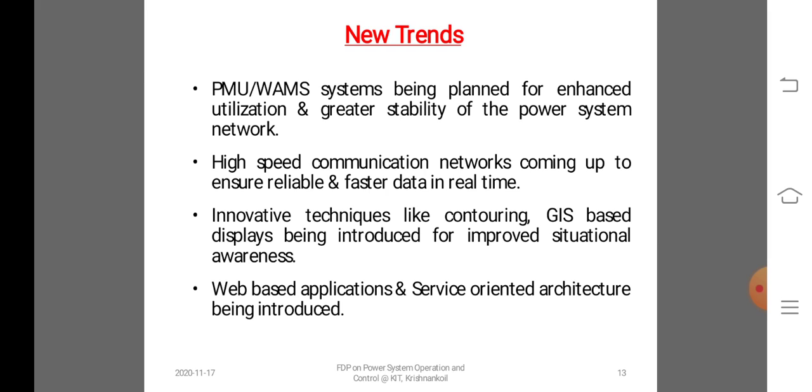Security enhancement recommends corrective control action to be taken to alleviate an existing or potential overload in the system while ensuring minimal operational cost. Then calculate the impact on losses if the output of a unit were to be increased by 1 megawatt. Then short circuit analysis determines fault current for single phase and three phase faults for fault locations across the entire power system network.